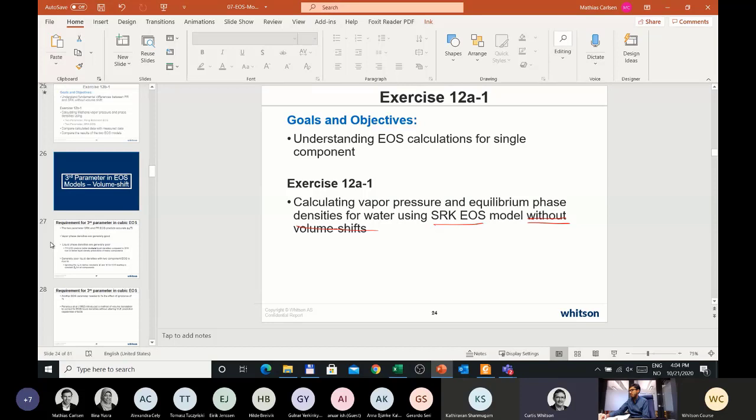So for water, okay. So what I understand is, except for that partitioning, it doesn't have any other specific advantage. So in that case, if polar components are present, is it better to cross-check with CPA only for that specific aspect and do the other simulation with SRK or Peng-Robinson, or how will it work?